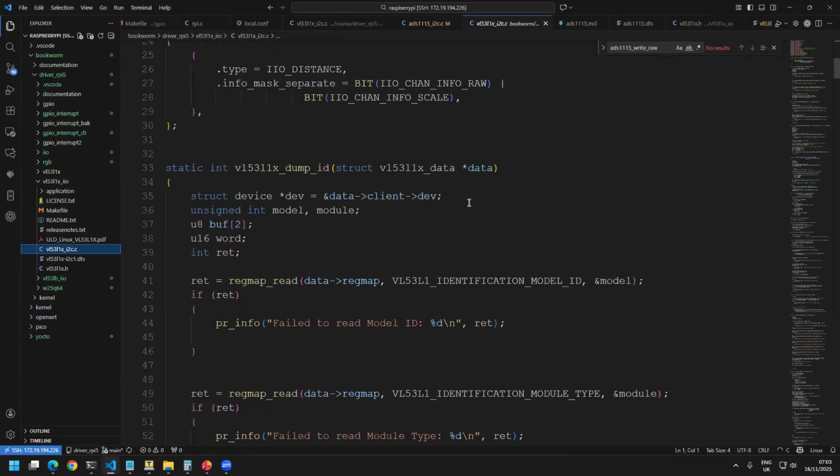So this is one of the very complex codes. So VL53L1 is the name of a sensor, a time of flight sensor. So this is used for measuring the distance of any device. So what happens is it basically has one photodiode and one laser unit.